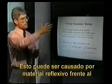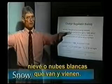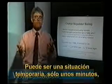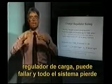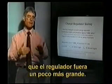This can be caused by reflective material in front of the module, white sand, white rock, snow cover, or white billowy clouds that might come and go. It can be a temporary situation, only for a few minutes, but if that current level is too high and stresses out your charge regulator, it can fail. And your whole system reliability is shot simply because you didn't oversize your regulator by a little bit.